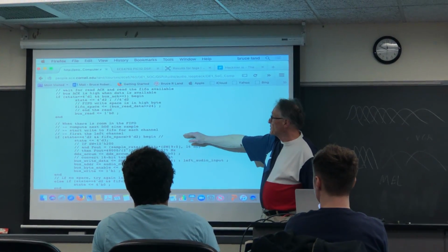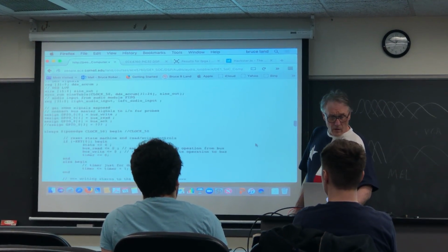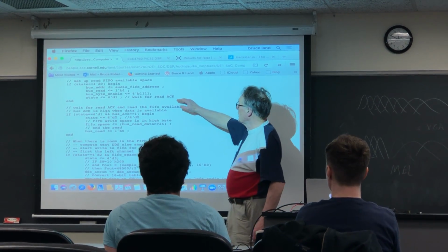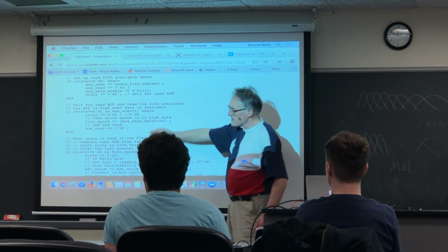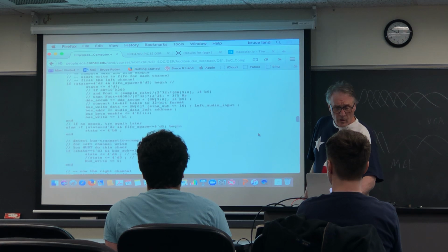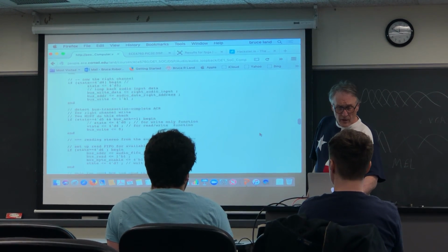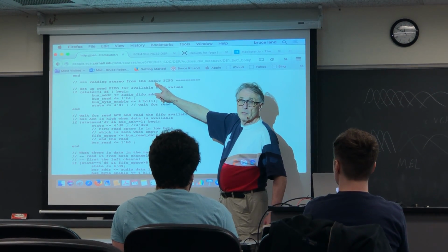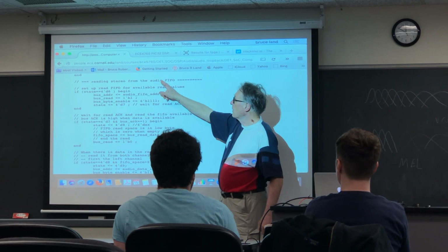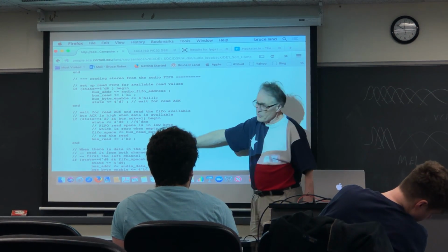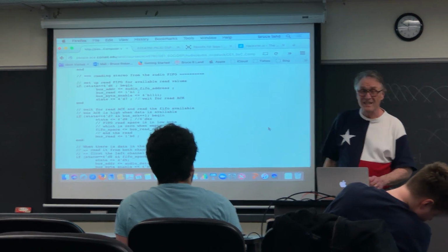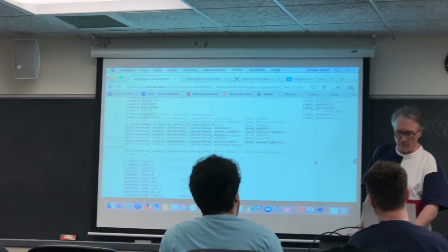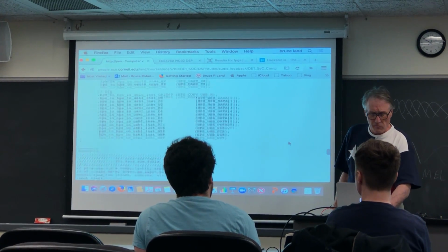We started out, of course, by just reading from the FIFO, or getting the FIFO space, and then writing the new sample to the FIFO. But there's one added thing here now, and that is to read the stereo from the audio input, because this is doing a loop back, taking audio in and putting audio out. So this code then reads the input ADC from both channels. That's the usual structural coding stuff.